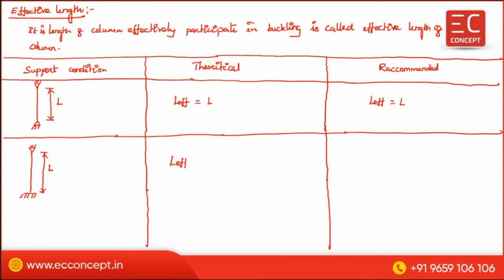Here L effective theoretical is equal to L by root 2, which is 0.7 L, but L effective recommended is equal to 0.8 L.